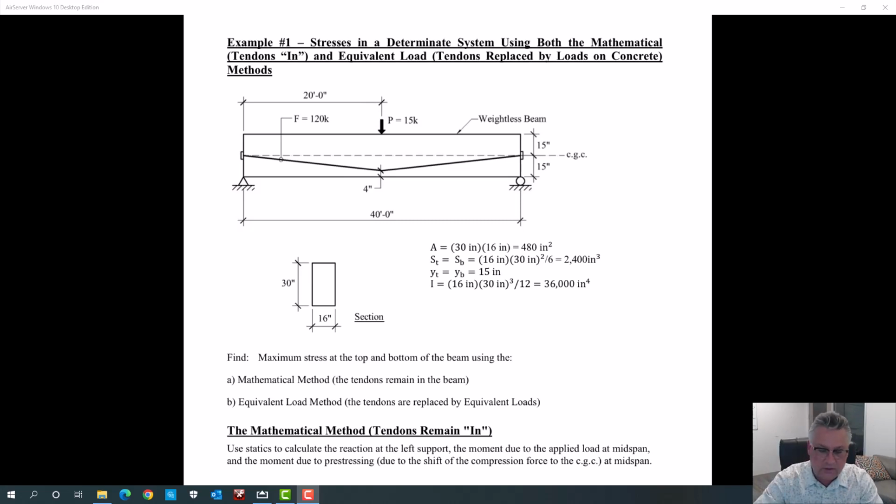And hopefully I've set the stage that we will have equivalent loads. That tendon force will be pushing on the concrete. This actual applied load is also pushing on the concrete in the opposite direction. As far as the concrete is concerned, that equivalent load is as real as any other load, but it's not. You know better. Concrete's not as smart as you are. Concrete thinks it's a load happening to it. Concrete doesn't think in terms of the fact that it itself is pushing back on the tendons and canceling out that load. It just thinks something's inside it pushing up on it.